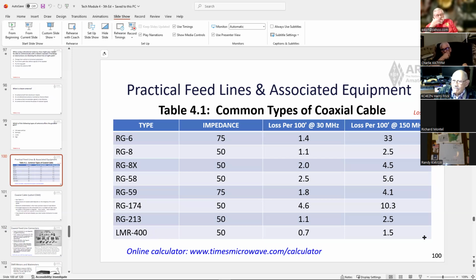If you have an antenna with 3 dB of gain, that means it's doubling the effective power. But you've got to remember, when it comes to gain in an antenna, it's effective power in a given direction, basically where you're pointing that antenna. And the more gain a given antenna has, the narrower that effective direction is.